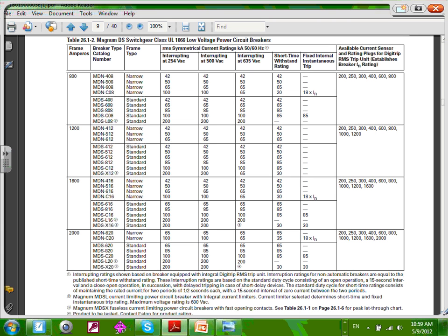Look, you can't buy anything less than an 800 amp. Look how they start with an 800 amp. This is called the frame size, the frame amp. 1200, 1600, 2000, and underneath it they go higher. So I can't emphasize, these are called frame size. This means how big physically the circuit breaker is. Doesn't mean anything. Right in here actually is what matters.